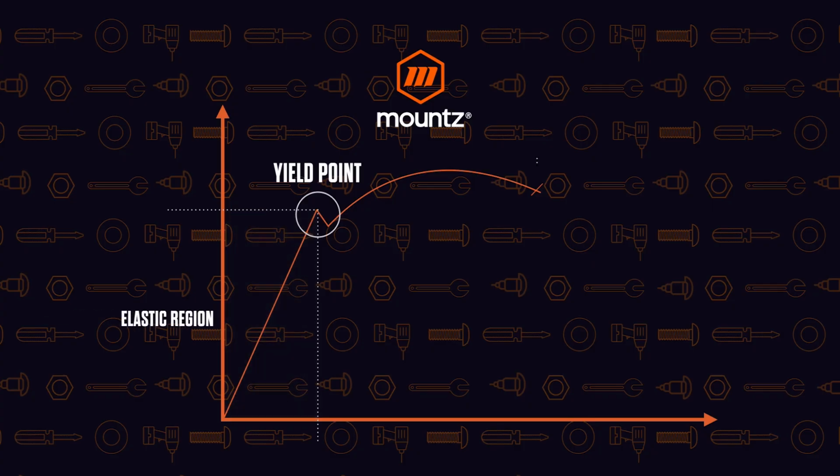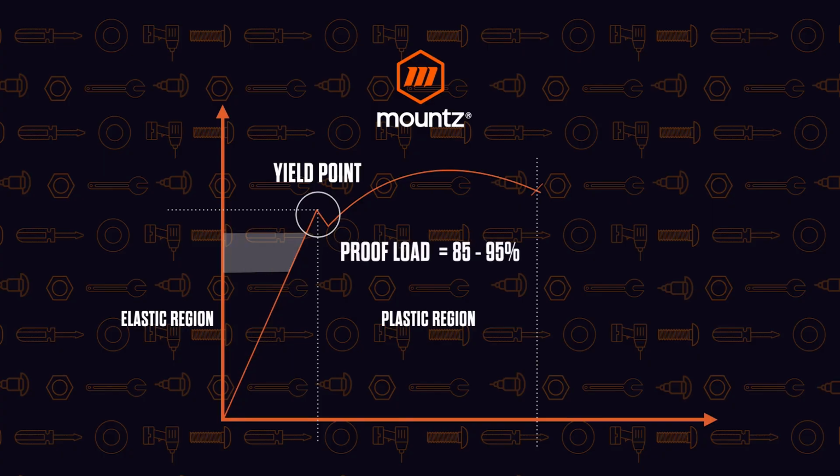Often fasteners are referred to as almost like a rubber band. You can stretch that rubber band, and if you remove the tension, it will go back to its original shape. However, if you take it past its yield point, the rubber band may break or it will not return to its normal size. Typically a fastener has what is called a proof load rating, which is about 85 to 95% of the yield point. If we stay within that amount of tension on the fastener, it will stay within its elastic region.